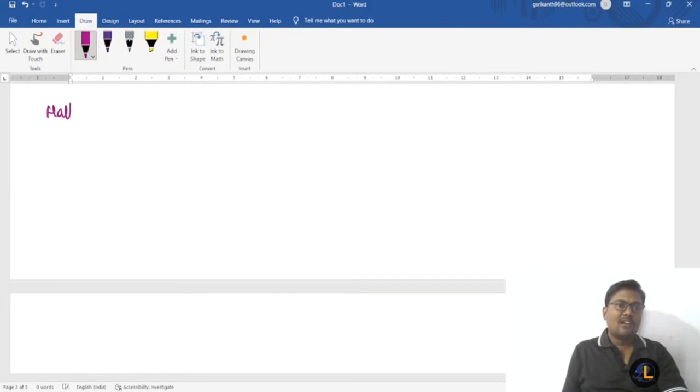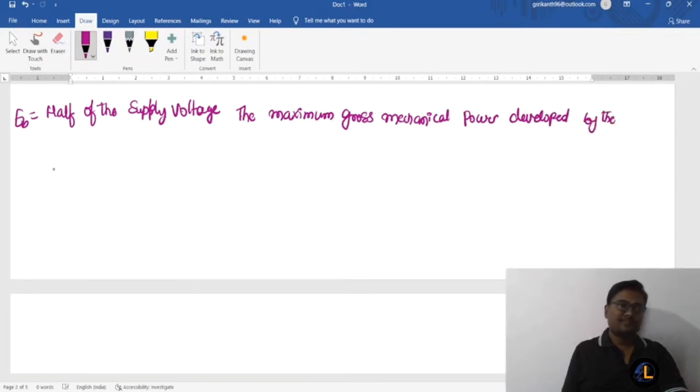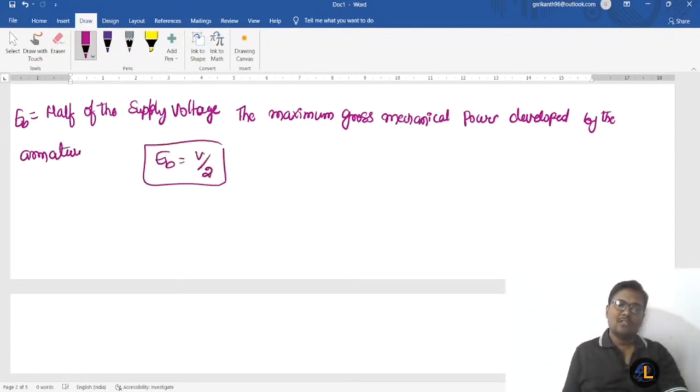So if EB is equal to half of the supply voltage, the maximum gross mechanical power is developed by the armature. So this is very important: EB is equal to V divided by 2. In the next lecture we will discuss the torque equation of a DC motor. Thank you guys.